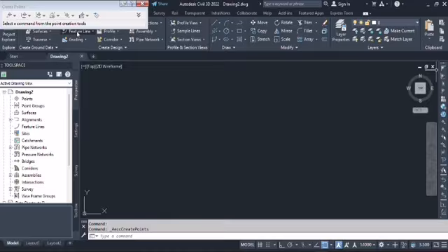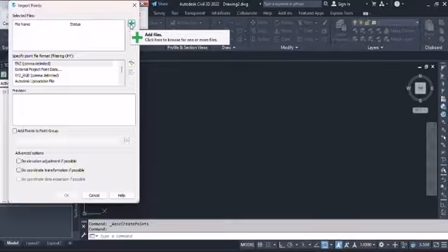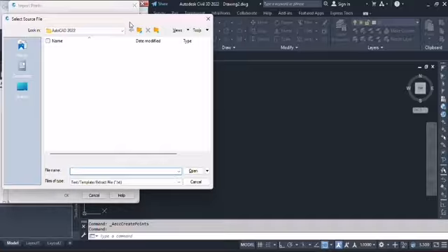It opens a new tab. Then from this tab, there's an icon which is written import points. Usually it's at the last icon. So you click import points. It opens another tab which consists of the import points tab. So from there you will be able to see some different icons on your right side. Our major icon will be this one, the green arrow, which is also known as the add files icon. You click on the add files icon.